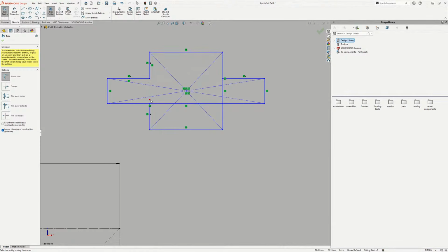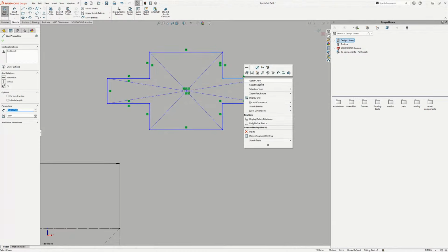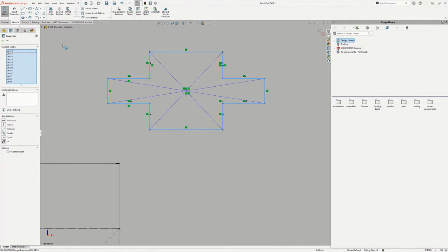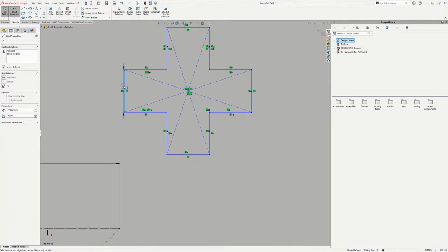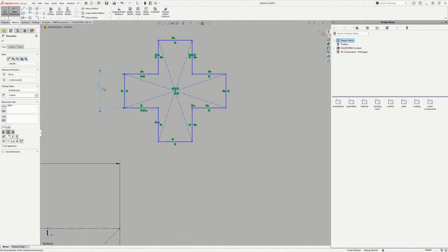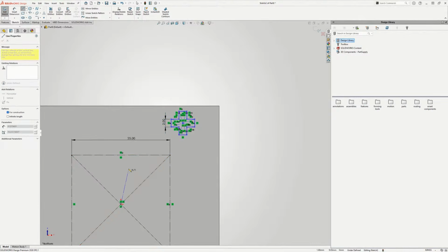Yeah. I've done these a few times now. Then okay, right click, chain. That's the great thing. We just chain select, make all these equal, and that's it. It's a nice tip to do a chain selection and then just hit equal. Yeah, for this it's very useful, I would say.